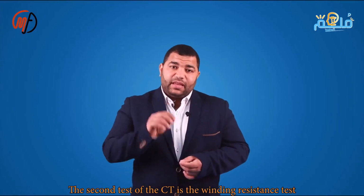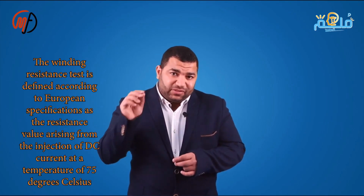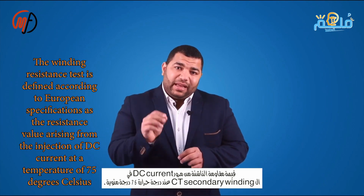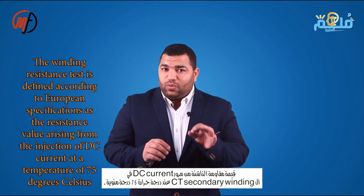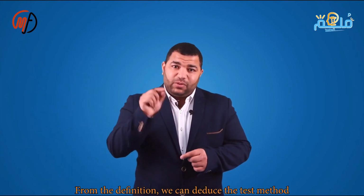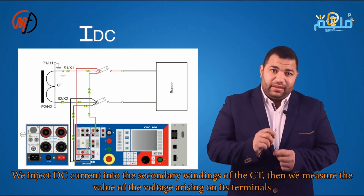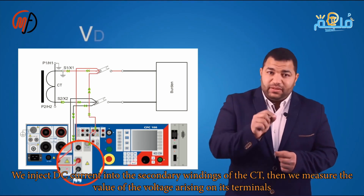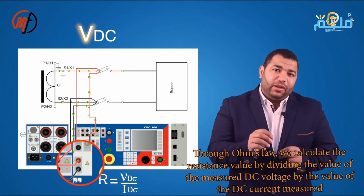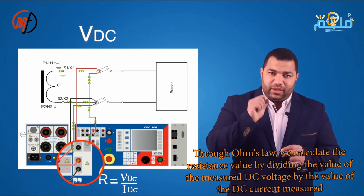The second CT test, the winding resistance test, is defined by European standards as the resistance from DC current flow at 75 degrees C. The test involves injecting DC current into the CT secondary winding and measuring the voltage across its terminals. Using Ohm's law, the winding resistance is calculated by dividing the measured voltage, VDC, by the current, IDC, from the ammeter. The resistance is then adjusted from the site temperature to 75 degrees for comparison with the factory report. Site temperature is measured using a thermocouple connected to a Fluke multimeter.